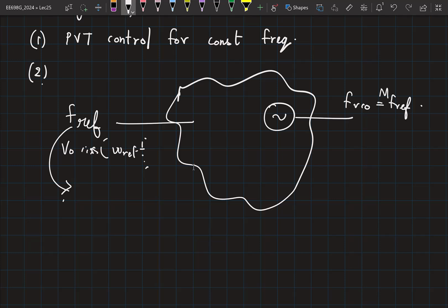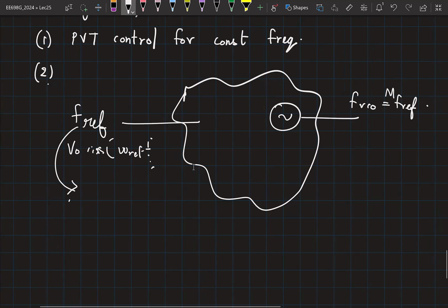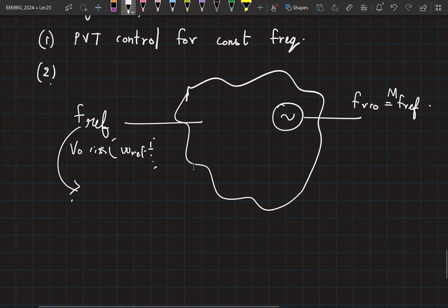They cannot be integrated onto our regular bulk CMOS process. So one, they are bulky off-chip components. So if you want to put 5 different frequencies and you choose to have 5 quartz crystals, then your chip might be small, but the board on which you have placed your chip will be large, right? Which means the size of your phone is not going down, right? Because the PCB inside is larger. So because of these reasons, we typically have one crystal source for a chip, right?